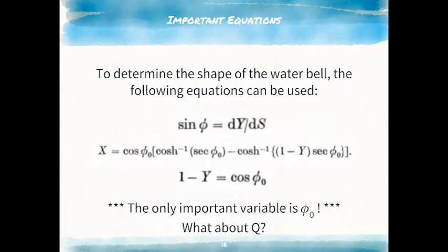From experimentation, we also found that different cone sizes required varying amounts of water to achieve the water bell formation. We were able to calculate various flow rates, and we'll discuss this at a later point. One of the most important factors to the success of our experiment is creating small diameter laminar flow onto the cones. Water straight out of the faucet has some turbulence and an uncontrollable diameter, so we made a nozzle to control and direct the flow.